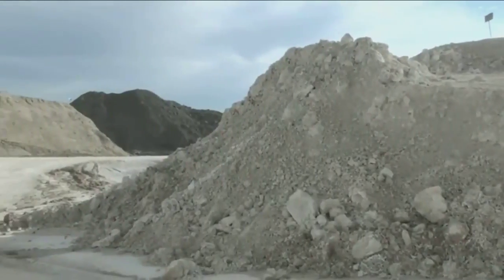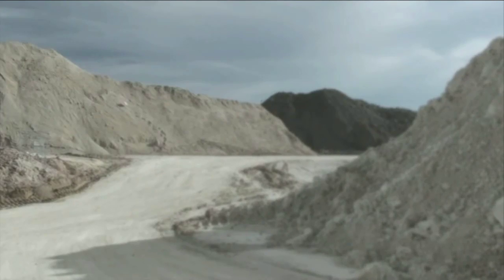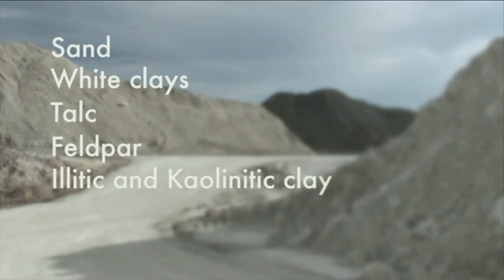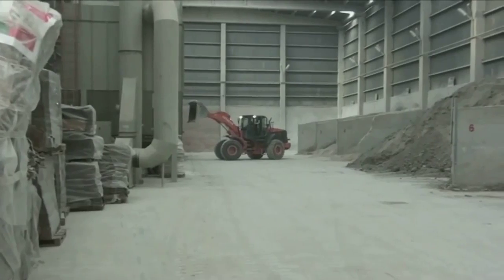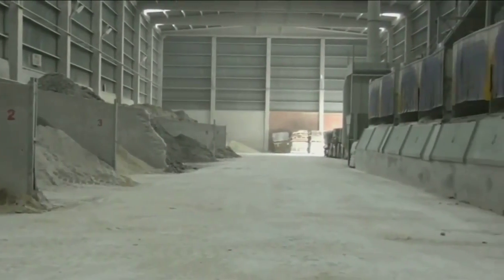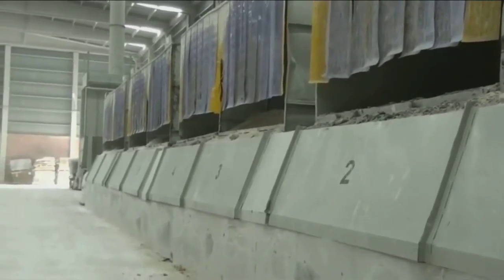Tiles are made from basic components that are readily available from Mother Earth. Raw materials such as sand, white clays, talc, feldspar, ilitic and kaolinitic clays, calcite, and dolomite are quarried and refined. Using heavy construction equipment, the raw materials are brought to the plant where they are stored prior to mixing. They are placed in holding areas, classified by type using a simple numeric reference system.